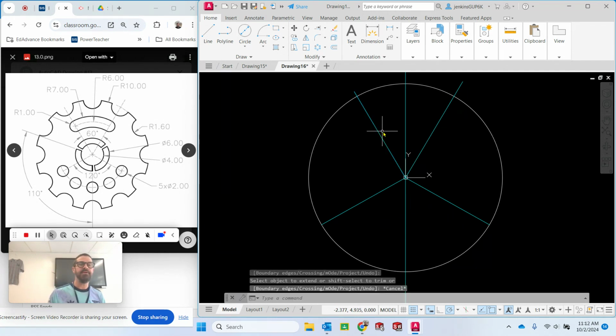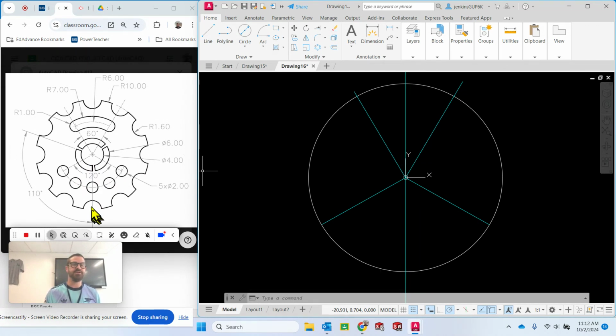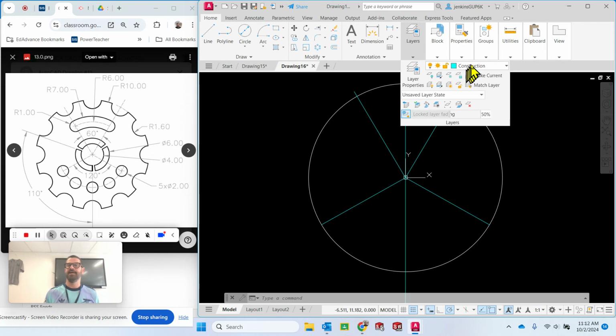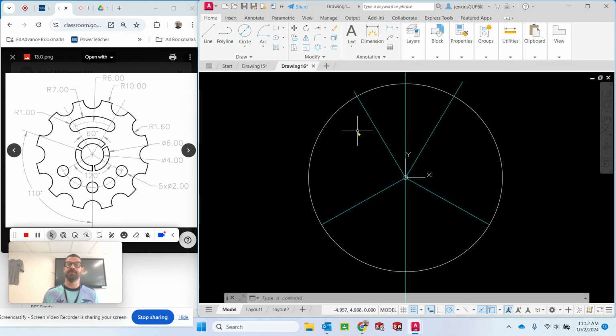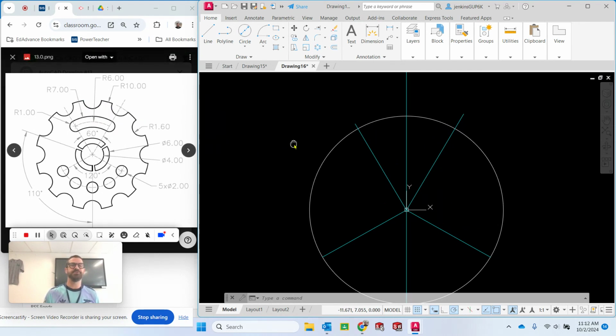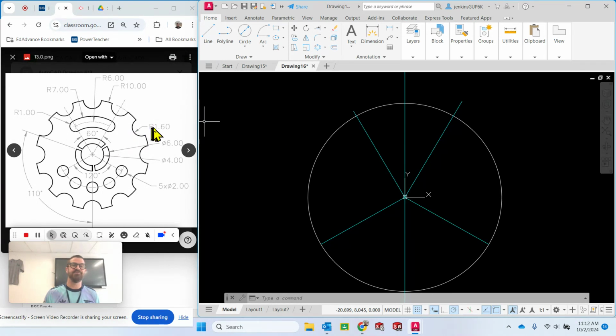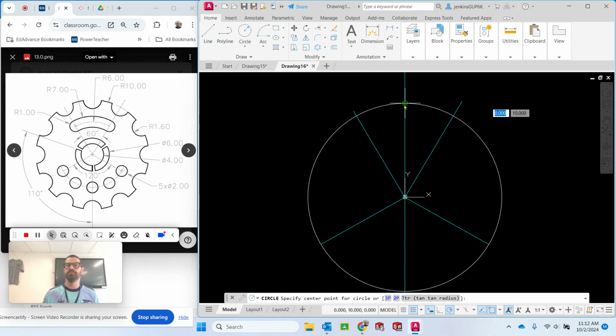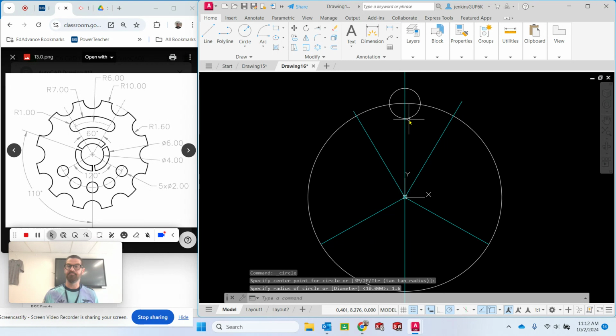All right. The only other ones that I could make at this point would be the one that goes straight down here and up at that angle. I might even just pause and not do those yet. Okay. All right. So I got some construction lines gone, and I'm gonna go back to my visible layer, and I'm gonna start by making this little semicircle, and it says that my semicircles have a radius of 1.6. So I'm gonna go to my radius. Cool. Say 1.6. Awesome.